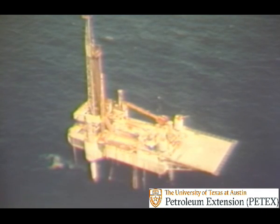On offshore rigs, seawater is used to make up mud. Seawater weighs about 8.56 pounds per gallon, 64 pounds per cubic foot, or 1.03 kilograms per liter, and contains many substances in solution, like sodium, chlorine, magnesium, potassium, and sulfates.